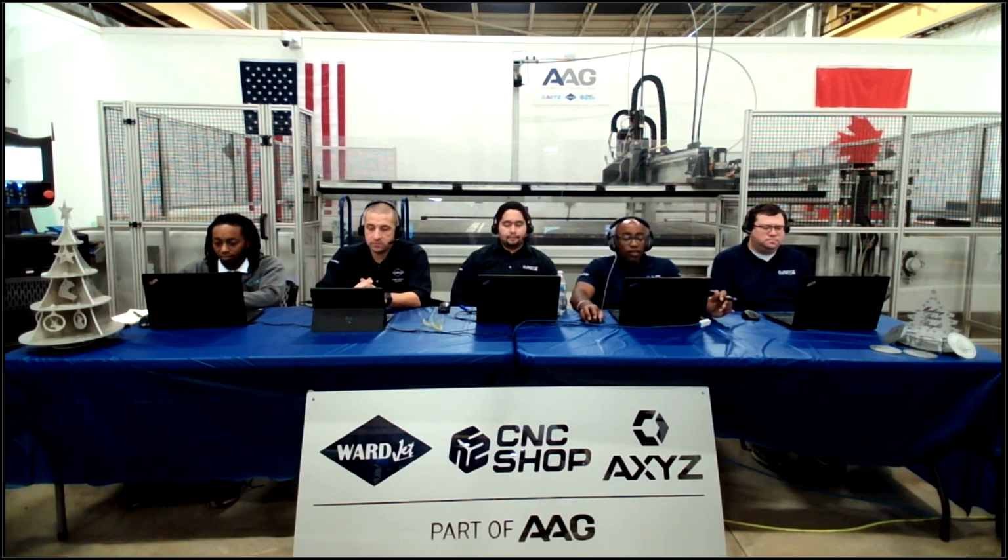Cutting clean pockets out of polypropylene. Kevin? Say an O-flute tool, for sure. And why we want to go with an O-flute is typically when we cut plastics, we have larger chips and we want to avoid rewelding. So using anything like a 2-flute or 3-flute, although you can, an O-flute would typically give you a nice clean cut.